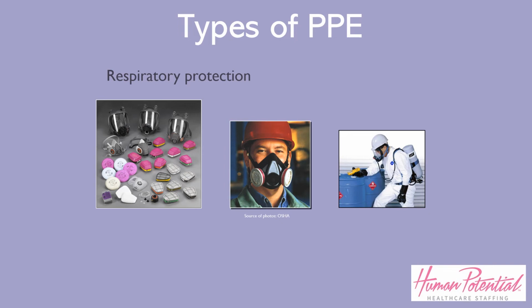Gas masks are also known as air purifying respirators because they filter or clean chemical gases out of the air as you breathe. This respirator includes a facepiece or mask and a cartridge or canister. Straps secure the facepiece to the head. The cartridge may also have a filter to remove particles. Gas masks are only effective if used with the correct cartridge or filter.